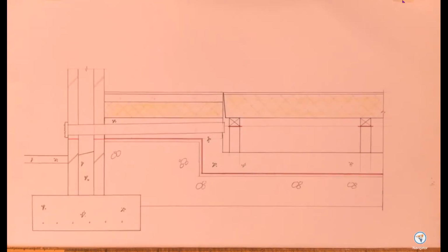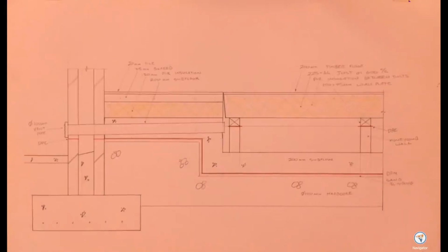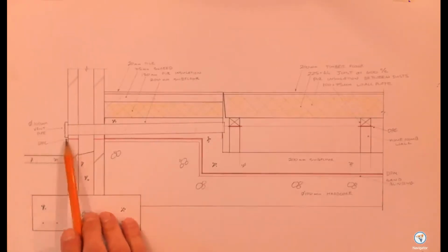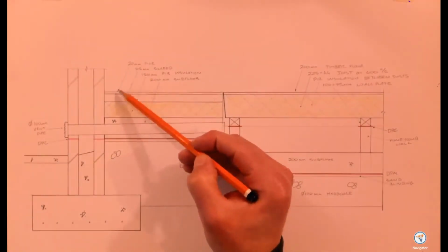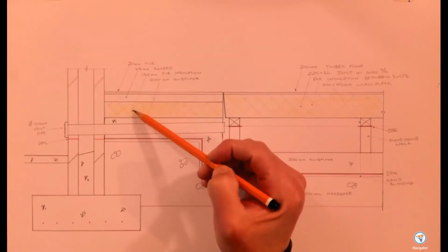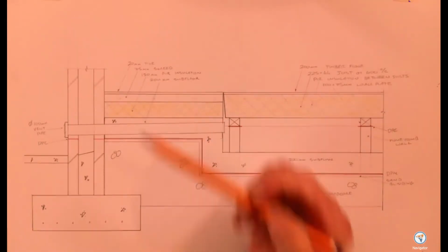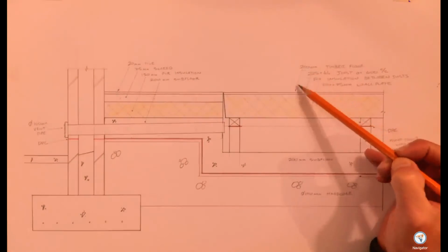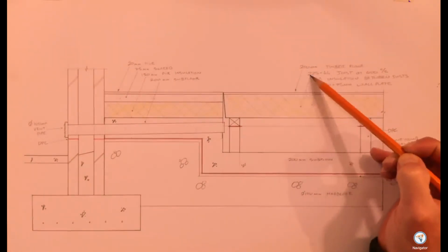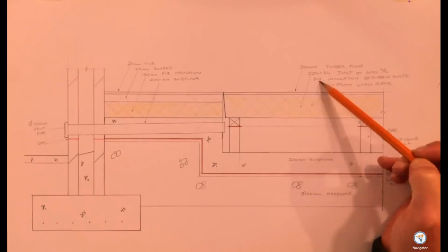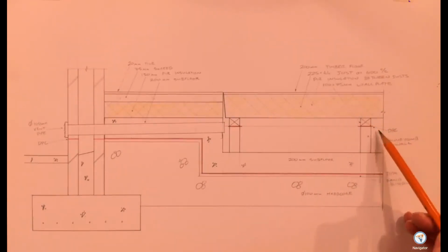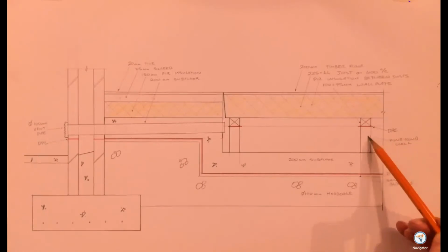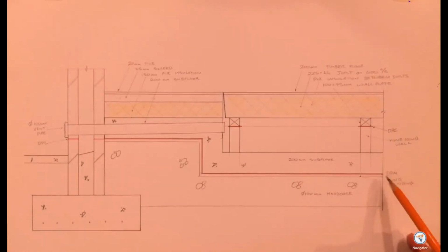Last thing to do is just put in all my labels. Okay, so the drawing with labels, the important labels: your damp proof course, diameter 100 millimeter vent pipe. We've got our 20 mm tile that was outlined in the question, 75 mm screed, 150 millimeters of insulation, 200 millimeter subfloor. On the other side, we have our 20 millimeter timber floor, 225 by 44 joist, PIR insulation in between the joists, and then we have our 100 by 75 wall plate. We've got damp proof course again, we've got our honeycombed wall, we've got our damp proof membrane, and we've got our sand blinding.